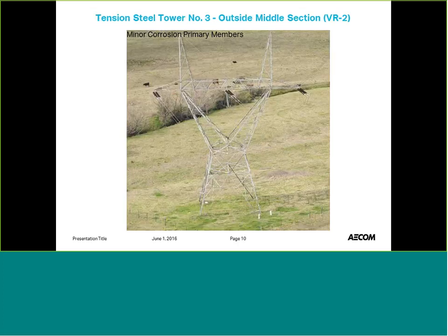This is now a tension structure. As I mentioned to you before, look how the strings are. They've been cut, they've been terminated. That's a tension tower. There's a lot more load. Typically, a tension tower is an angled structure. They've got to take a lot more load. They're a stay-type structure. In other words, if you lost conductors, these structures are designed to hold onto those conductors. They're a much broader, bigger structure. Traditionally, they're the smaller of the two in height, but 2 or 3 times the weight in steel. And the foundations are larger, of course, to handle compression and uplift.